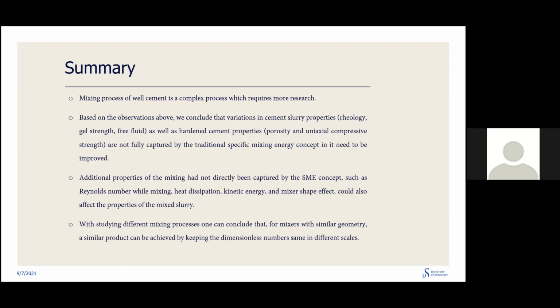So, all in all, mixing a well cement is really a complex process, which requires a lot of research and resources to spend on. And based on our observation, we concluded the variation of the cement slurry properties such as rheology, strengths, free fluid, porosity will be affected by how you mix it.